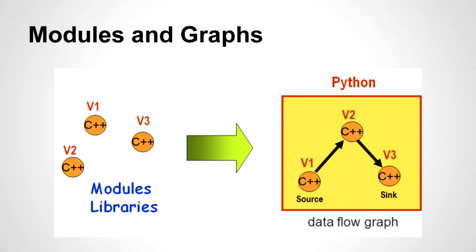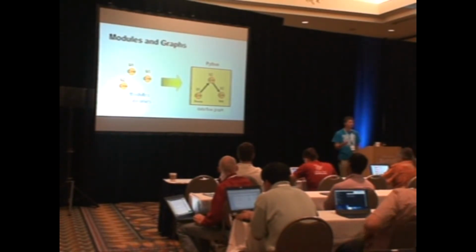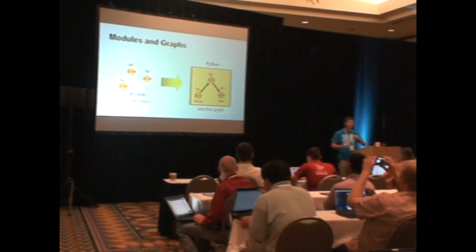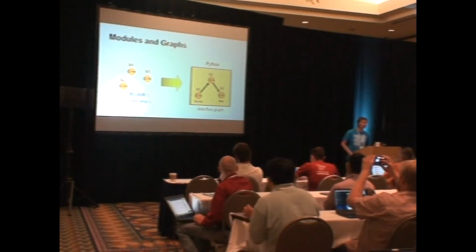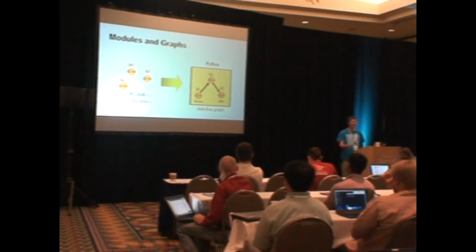So what we're showing here is that the data is flowing from block to block. The communication method, which unfortunately I don't have a slide on, is basically the blocks end up sharing a piece of memory. And the scheduler is maintaining read pointers and write pointers for the blocks. So basically it knows where the read pointer is and the write pointer. And when it has enough information for the block to run, it will call the block and tell it to run on so many items. And then it will return, pointers get updated.